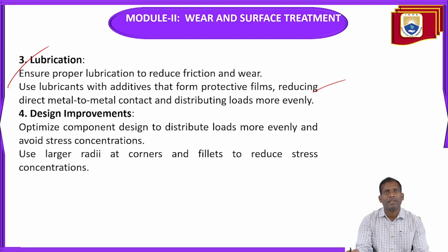So use proper lubricants with additives, so you can minimize the metal to metal contact. Wherever metal to metal contact is possible, there is friction and wear. So always you should apply lubrication to separate the metal and metal contact. Whenever you use lubricant between these two sliding surfaces, they will be separated and you can minimize the metal to metal contact.